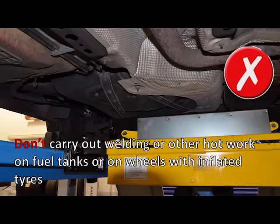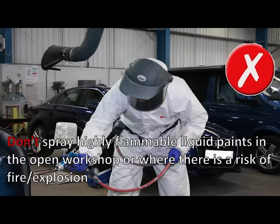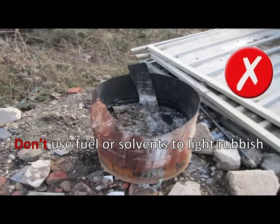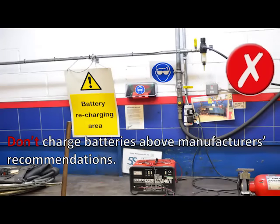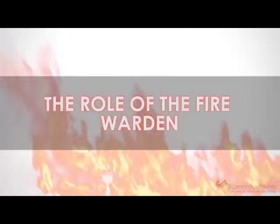Don't carry out welding or other hot work on fuel tanks or on wheels with inflated tyres. Don't spray highly flammable liquid paints in the open workshop or where there is a risk of fire or explosion. Don't use fuel or solvents to light rubbish. Don't charge batteries above manufacturer's recommendations. The role of the fire warden.